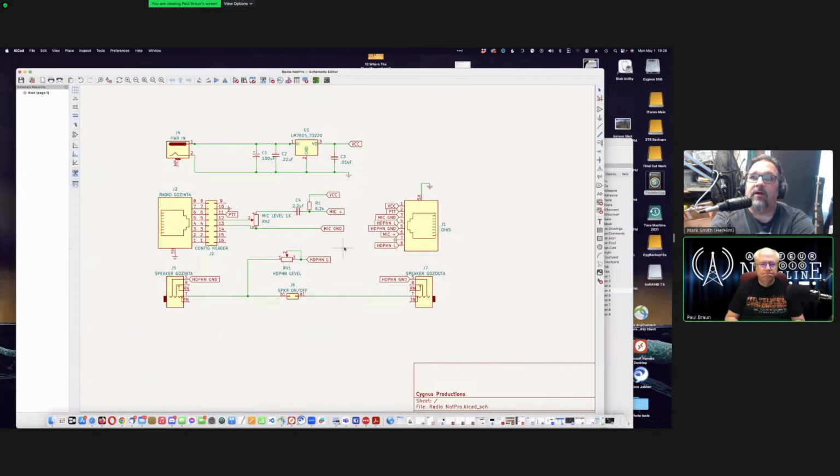Perfect. So what's the stuff between the J9 config header and J1 OHIS socket? This is the mic level trimmer. The OHIS standard says that the user side box takes whatever level your microphone is, puts it through a preamp, and sets it to a defined level, and sends that down the wire.